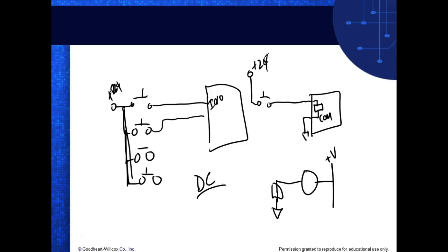DC, though, if you're dealing with DC, more and more we're going to DC-only inputs, and we're going to 24 volts. And why? Actually, it's below the NFPA 70E standard. That means if we're below 70E, we're not required to use any special PPE. Of course, then you're up to what the employer requires. So out at US Steel, you can't hardly work on anything without your hard hat on, your safety glasses on, and your metatarsals, right? But that's company policy.